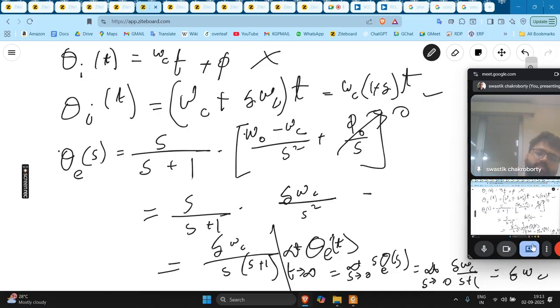So we see that when the frequency of the input is slightly different from the VCO frequency, it is perfectly tracking the difference in the frequency. So when the input frequency is equal to the free running frequency, the difference is 0. And when the input frequency is slightly higher or lower, then that amount of error is constantly maintained throughout the steady state.